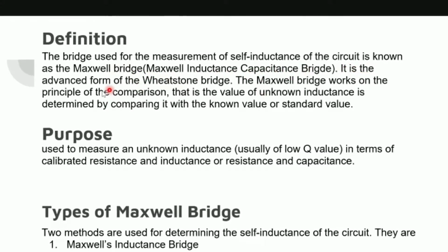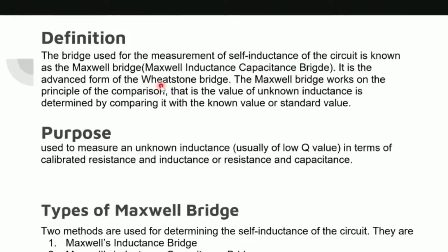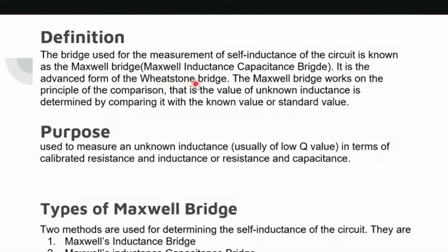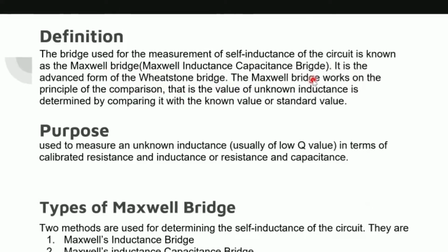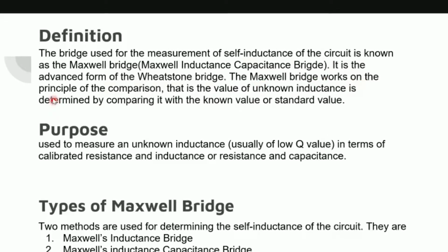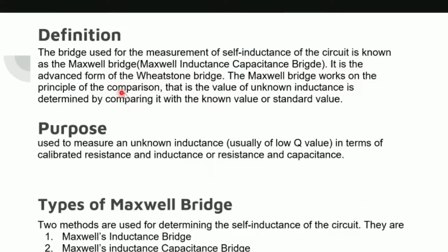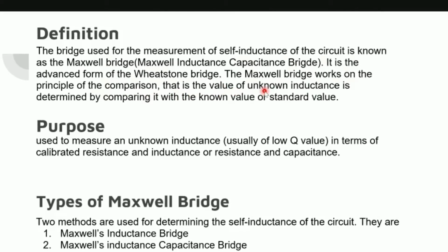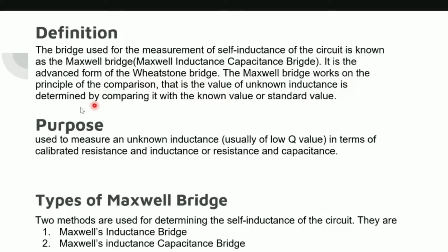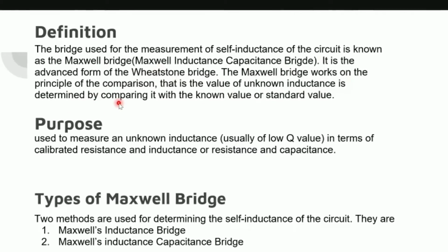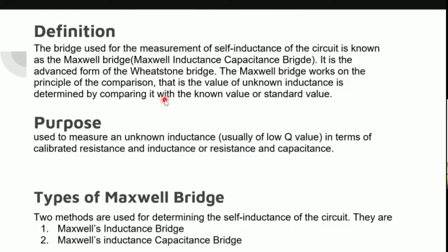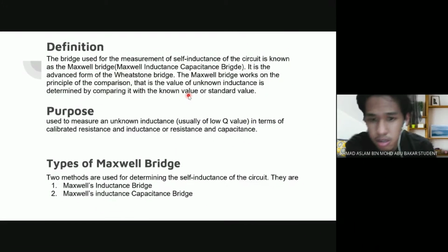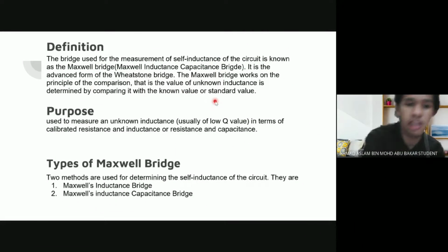It is the advanced form of the Wheatstone bridge. The Maxwell bridge works on the principle of comparison, that is, the value of unknown inductance is determined by comparing it with the known or standard value.